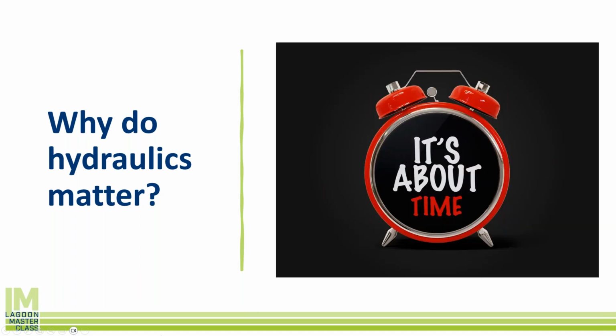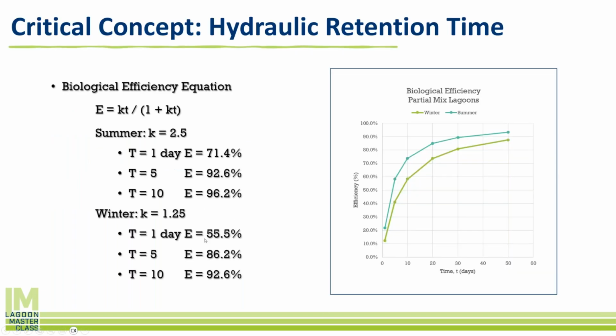The reason we're here talking today: hydraulics matter because wastewater treatment is about time. How long are we hanging on to the water, and what is the water doing while we're hanging on to it? And this is where we get into one of our most critical concepts here, and that's hydraulic retention time. This is important because if you take a step back and look at what we're doing here, we're not treating the wastewater. The bacteria that are in the wastewater are treating the wastewater. All we're doing is giving them the conditions they need to treat the wastewater effectively and predictably.